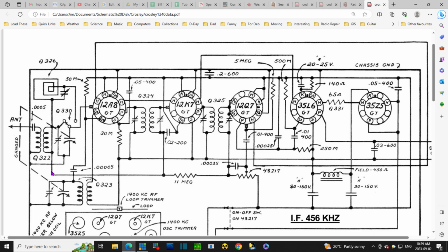If you follow it across, you get to the bottom of this coil. Now, I noticed this earlier about this schematic. If you follow the line up, you find a dot here. I think that's a mistake. I think that dot shouldn't be there. It should look like this, just going across. Because if this coil is hooked up like this, there's nothing here. This coil is not here. So I have to think this is a mistake. So what's happening is you're providing a... Now I'm silent again. As you're trying to get a signal to this point to go to the grid.